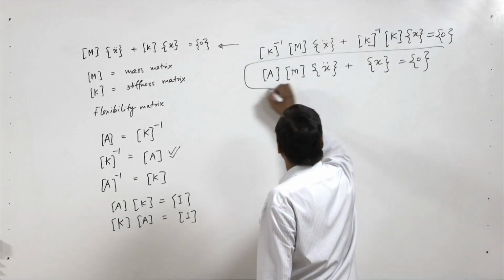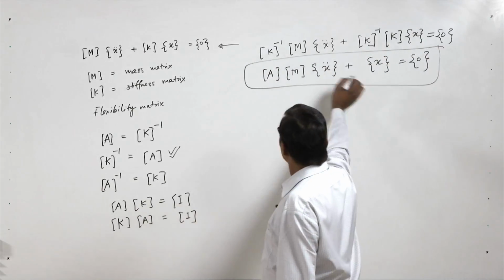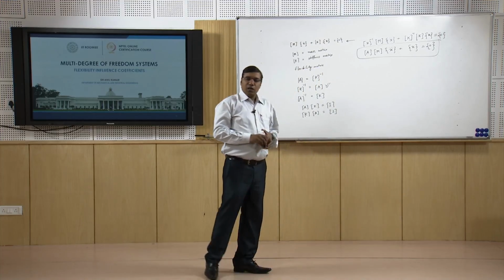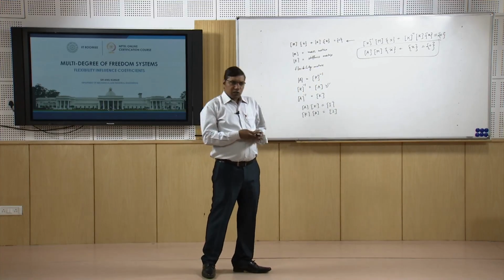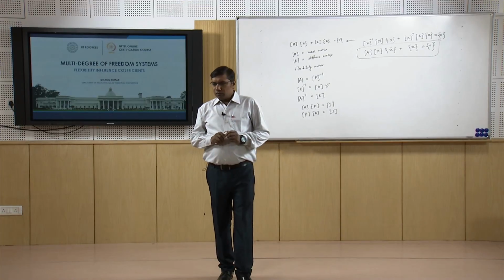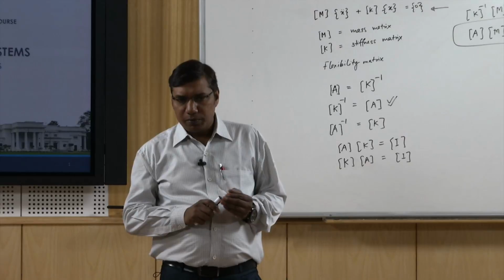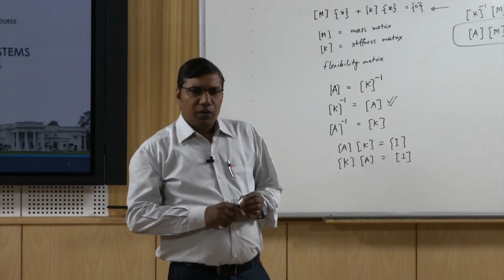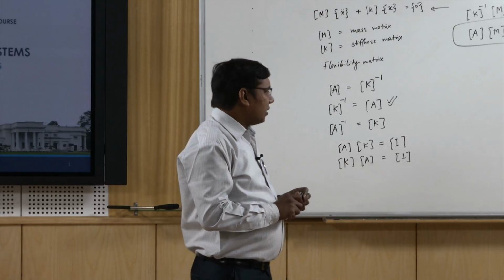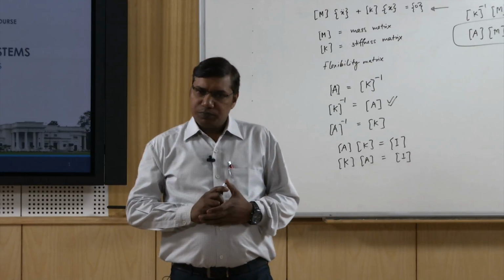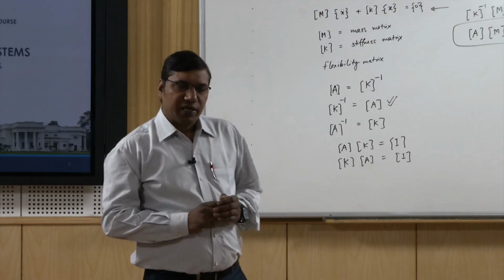So finally our equation of motion results in the form of mass matrix and flexibility matrix. Therefore if we can prepare the flexibility matrix, we can also write the equation of motion directly using the flexibility matrix.